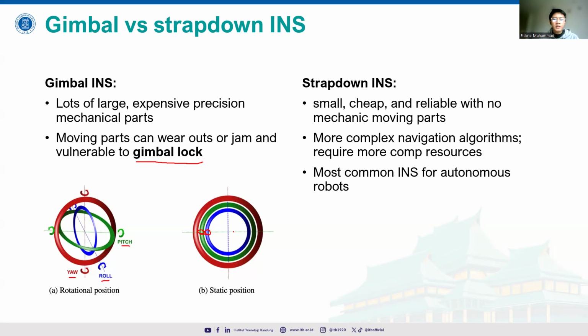As we discussed earlier, if we use quaternions, we can mathematically avoid gimbal lock, unlike Euler angles, because quaternions don't rely on a fixed set of axes and can smoothly interpolate between orientations, but we're not going to talk about that here. Or maybe we can also add a fourth gimbal to prevent the axes from aligning. But of course, it increases the mechanical complexity.